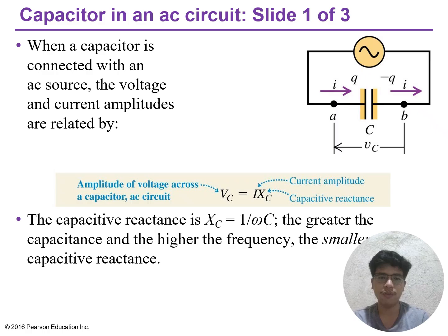At high AC frequency, charge flows constantly back and forth and the capacitor acts almost like a short circuit. The frequency-dependent nature of capacitive reactance makes capacitors useful for applications like frequency selection and filtering, as we'll see when discussing filter circuits.